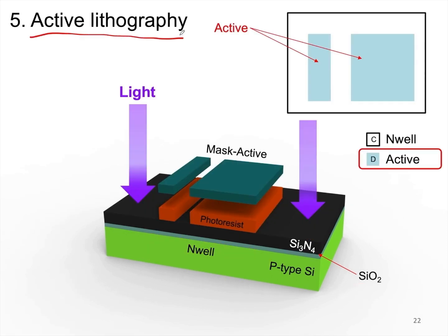For the active area photolithography, we need an active layer, right? This corresponds to a mask. Let's take a look at how we draw this layer. It looks something like this with two shapes, a rectangle and a square. These two areas represent our active region, which will be used to form our channel region, right? This part is used to form our substrate contact. This part is specifically used to form our substrate contact in order to effectively and efficiently create a connection.